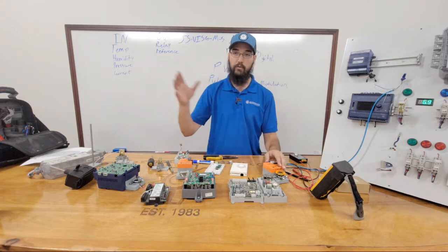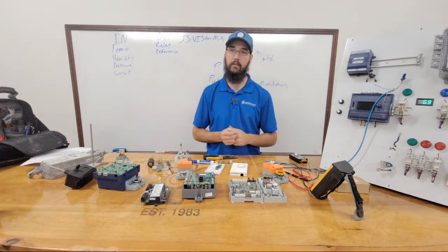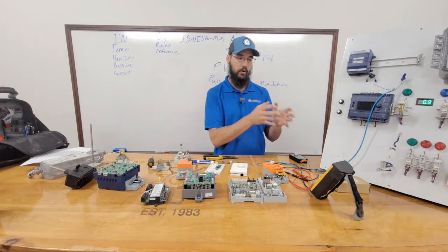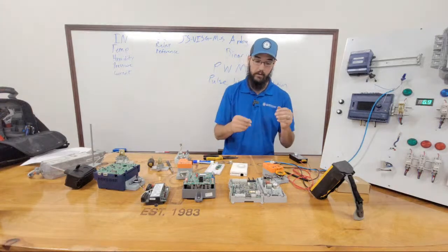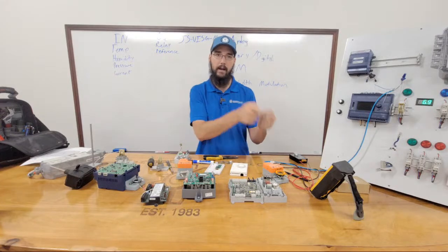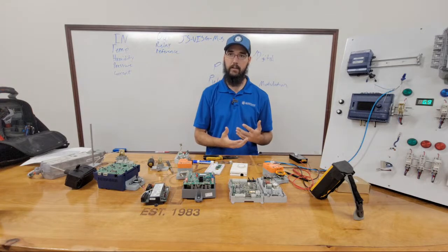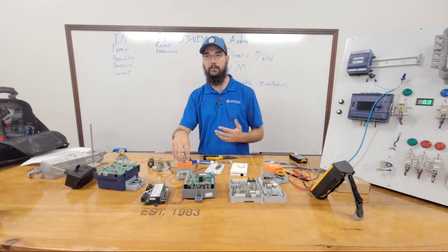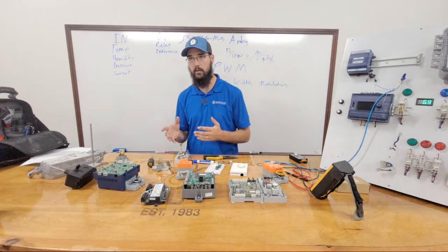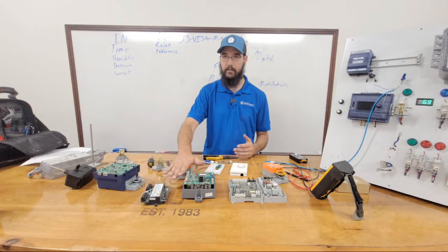Or maybe you go find an actuator in the same building that is working. You can confirm it's working, so you trust it. Pull that actuator, go over to the one you are working on and wire it in. You don't have to actually mount it where it needs to go. Just move the wires and wire it up. Does it actuate? Because if you can wire that controller into a different actuator and it does what it's supposed to do, then you've just eliminated that that actuator is the problem, not the controller.